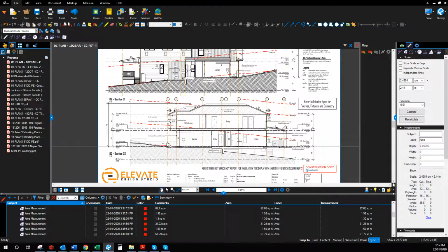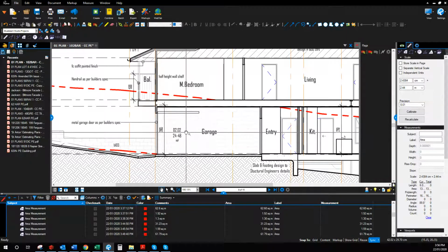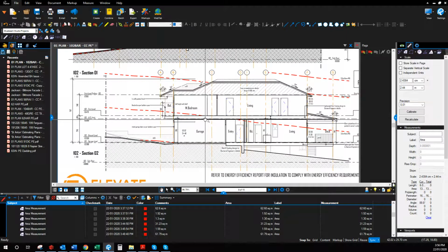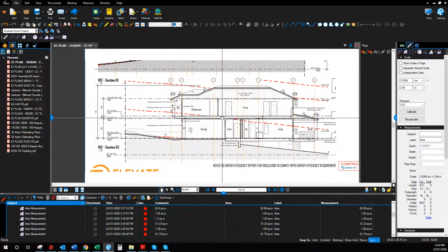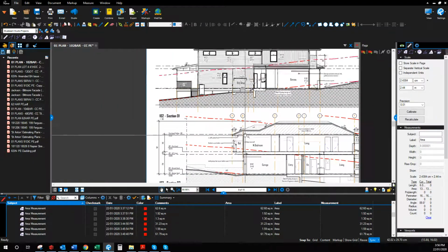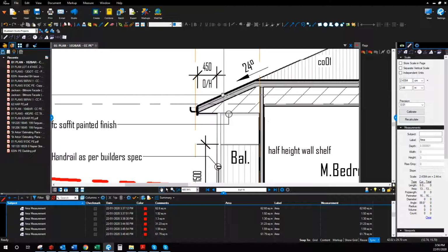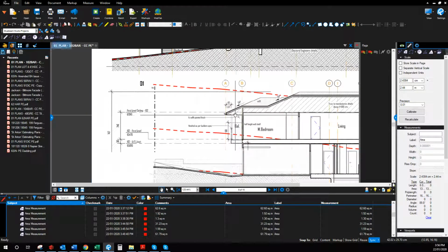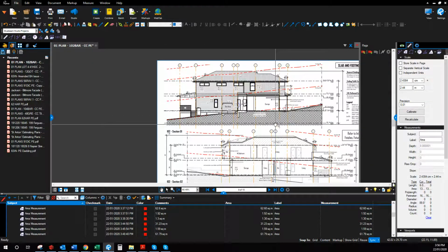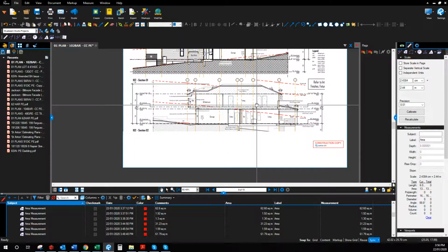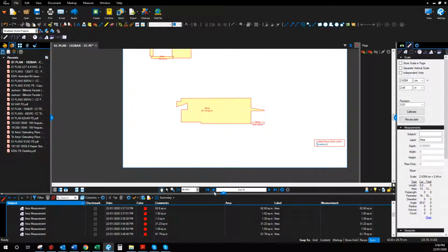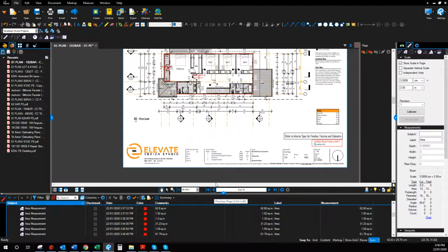With other areas, we don't really have a section to see whether or not the ceiling sits higher, and therefore we would have beams. Obviously along the front there will be beams up in this ceiling, but at the moment it looks like the beams sit up under where we're going to have our eave sheet or ceiling. So at the moment we'll just do the ones around the deck, and we'll note that that's the only area that we've done.